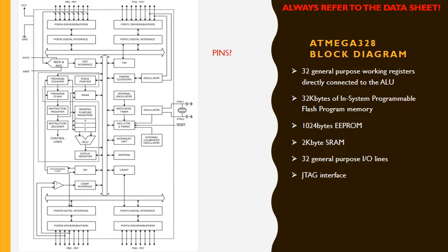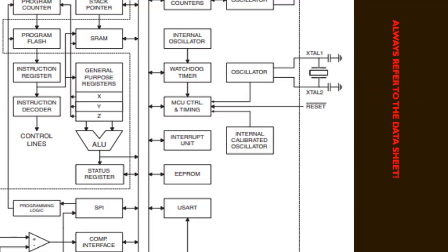One last thing. Here we have the flash and the SRAM. Yes, perfect. So I have the program flash and the SRAM. What can you notice about those two here? Program counter connected to program flash, makes sense. Why? Because the PC is used to know which instruction I'm going to execute next. What about the stack pointer? Does it ring a bell? What do you use stack pointers for? This is from last year. For the functions or the procedures. So hence it's connected to the data.